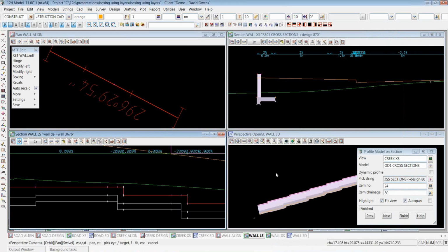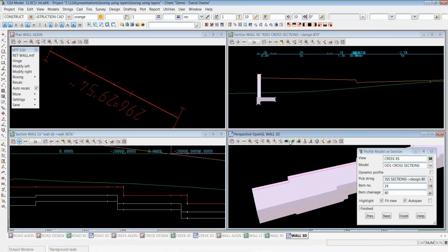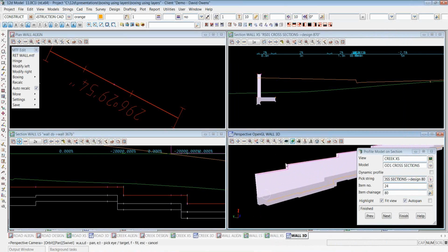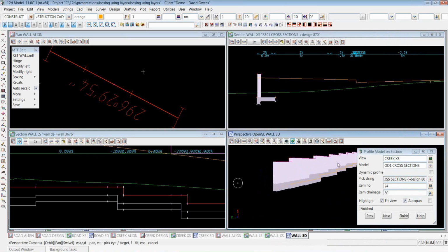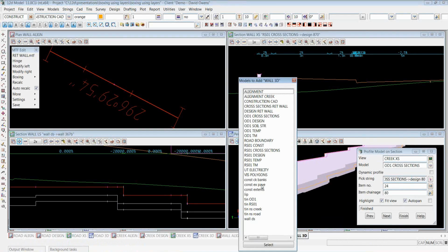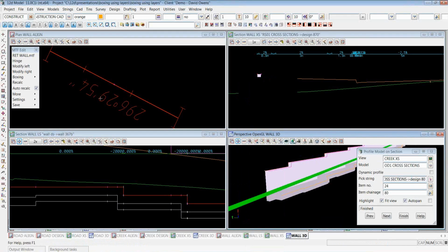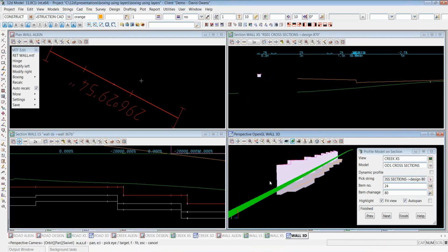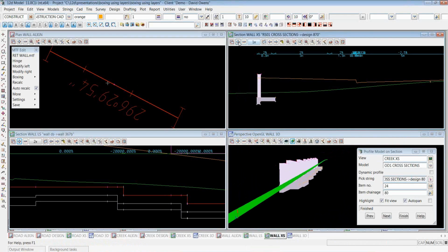Okay, and then when that all runs through, it creates an actual proper model. Now, why would we bother doing this sort of thing? Well, in this day and age, we have to be very, very mindful about service clashes. So in this case, I was able to have my electricity conduit modelled up at the standard depth down from the surface.